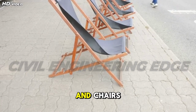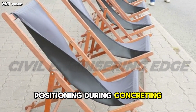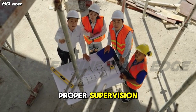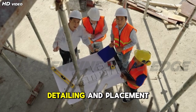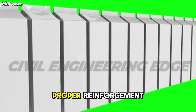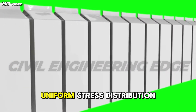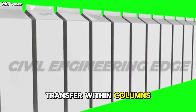Use of spacers and chairs helps maintain correct bar positioning during concreting. In practice, clear reinforcement drawings, proper supervision, and skilled workmanship are essential to achieve correct detailing and placement. Proper reinforcement detailing ensures effective bond, uniform stress distribution, and safe load transfer within columns.